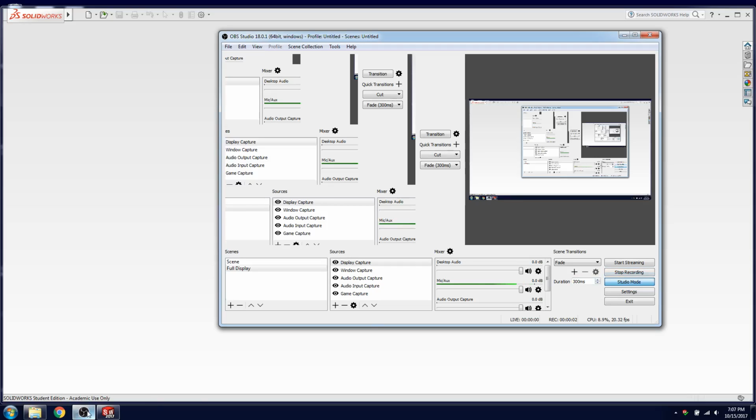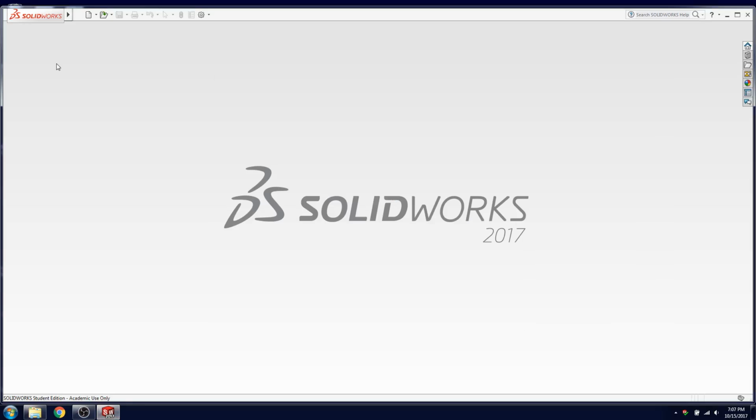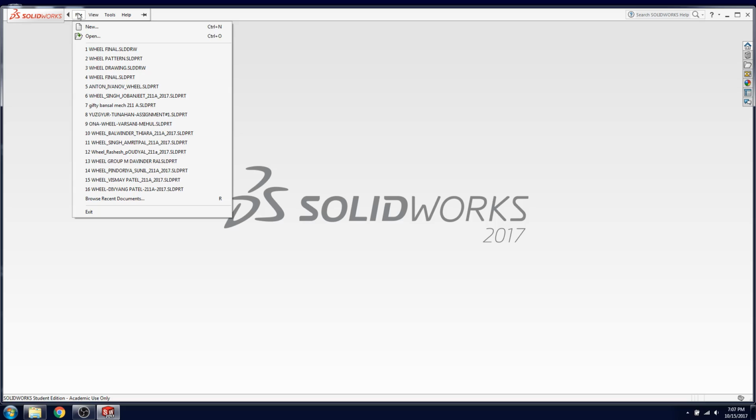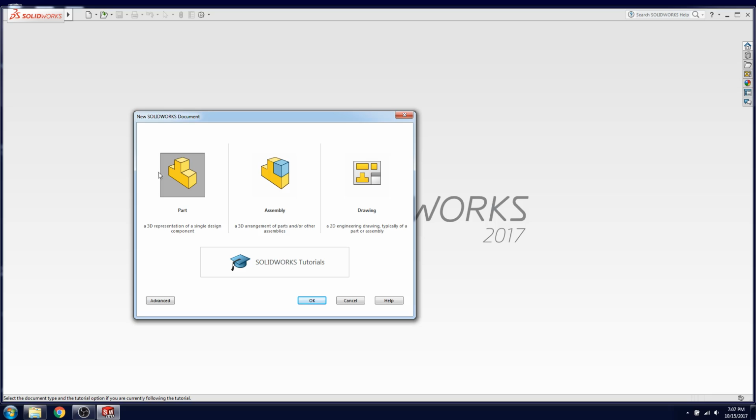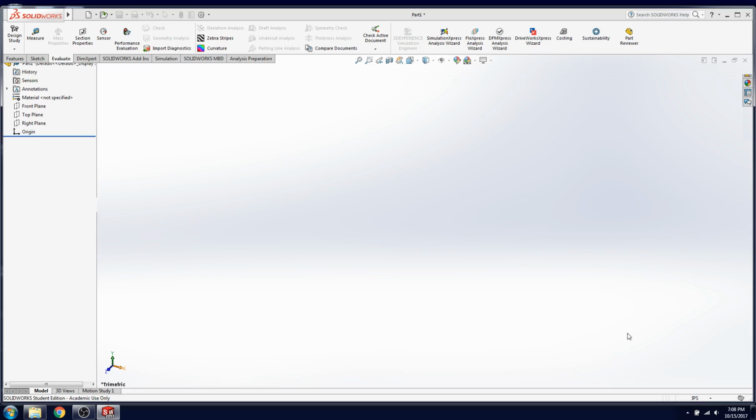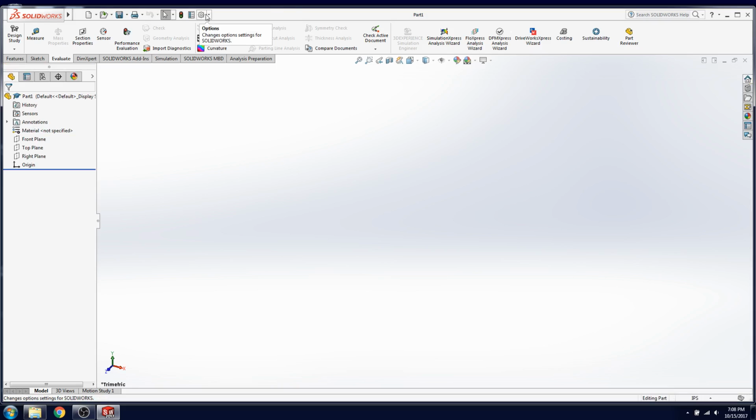In this session I will show you how to start your setup for 3D frame created on 3D Sketch. So first of all, anytime we do a frame that will be welded, we will be creating it as a part. So we open new part, and like usually we need to go and verify if we have a proper setting. We see here that this is inch/second, but you know that it may not be fully set up properly.